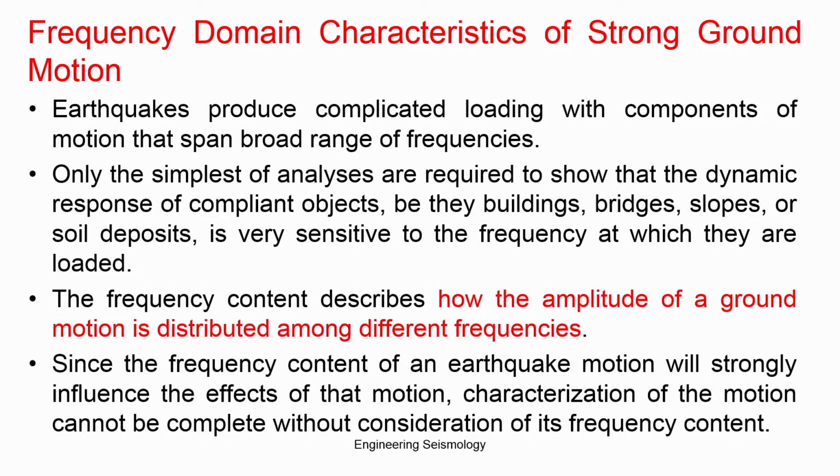If the earthquake frequency and the natural frequency are very close, you will get a very big response and may also get resonance. So depending upon the building we design, with its natural frequency, you need to identify what frequency range of the data you are interested in for the analysis.